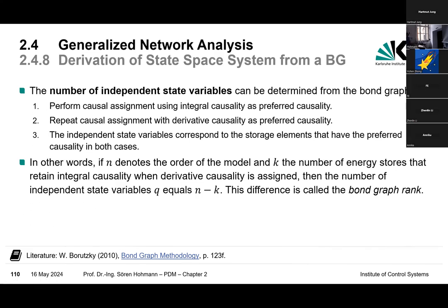Why is this important? Well, again, it's a computational question. So if you have something like Dymola or Simscape, then you know it's something like a bond graph, obviously. And if it's a bond graph, then you can do the causality assignment. The causality assignment, according to this procedure, is fully automatic, can be programmed easily, or has been already.